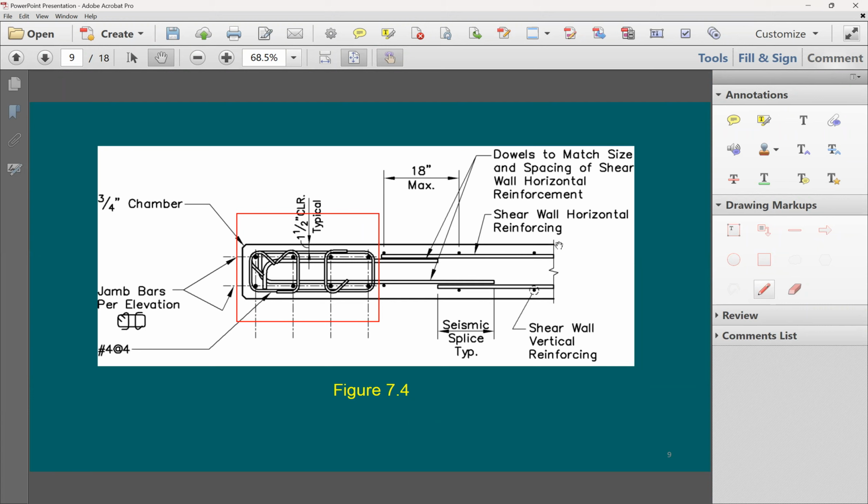Now, how do you find out the shear demand? Shear demand is going to be given to you most likely, unless you're doing seismic analysis for the shear wall for the building and then determine the amount of shear demand, which is V sub U. Now, how about the capacity? Capacity is determined based on the steel reinforcing that you put there, and also the concrete strength.